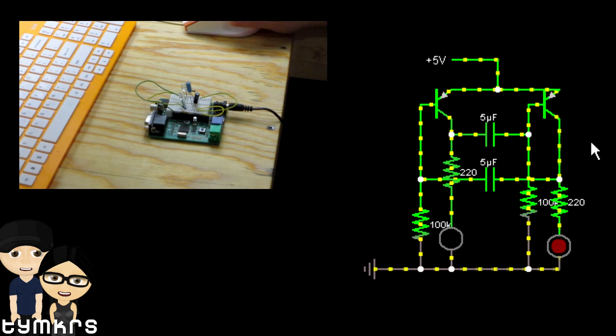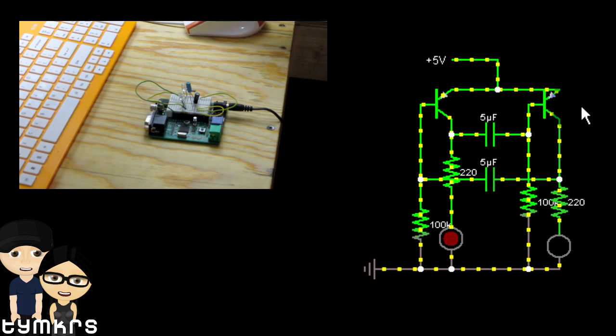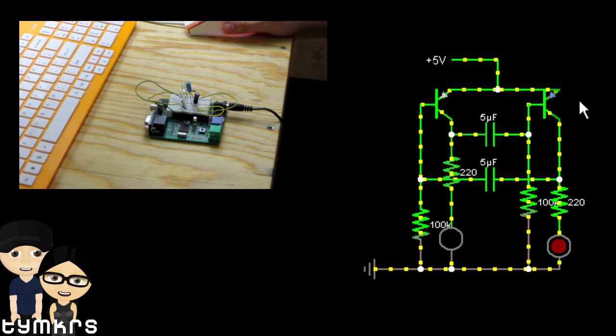And once one of these sides gets to the point where it turns off, you'll see no current goes through. But as soon as it finishes relaxing, and this voltage at the base gets lower than the emitter, the transistor allows current to go from the emitter to the collector.